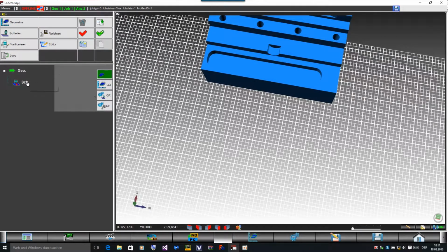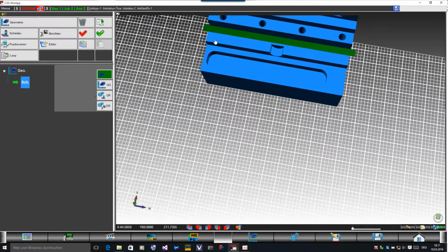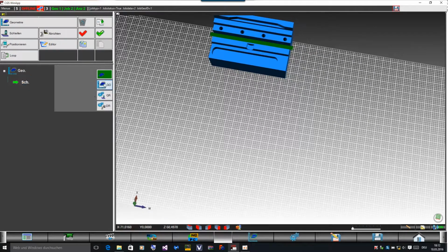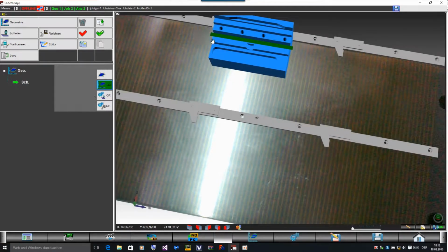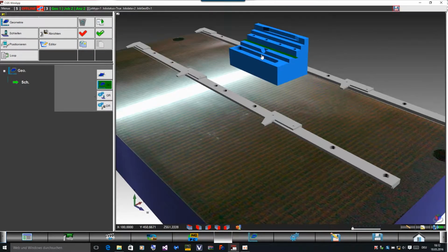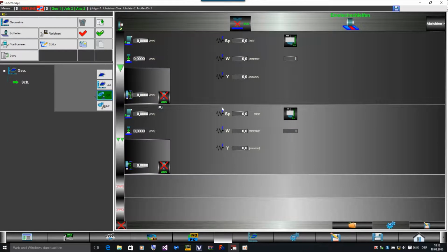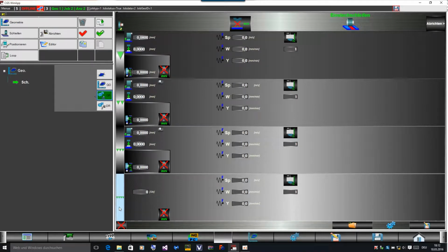If I see this, I have the grinding position already in the program. I can modify the data, or I can take over this in the way I get it from the 3D file. And then in addition, I set some technologies. Technologies is for roughing, finishing, fine finishing, and spark out. There is a lot of data you see here for downfeed and spindle speed, the speed for the double axis, and also the y-axis downfeed.